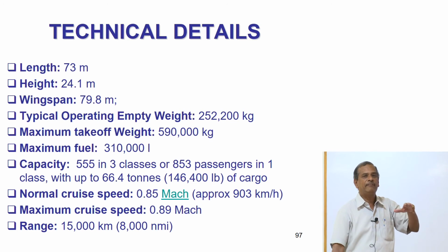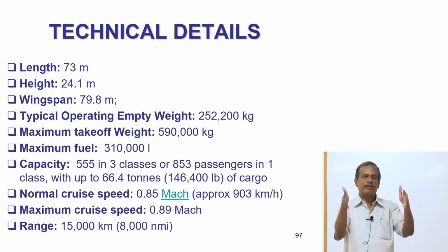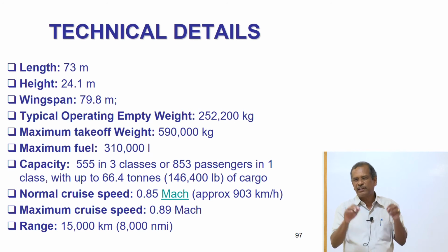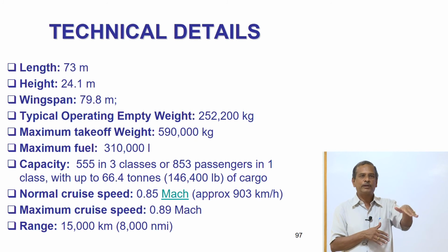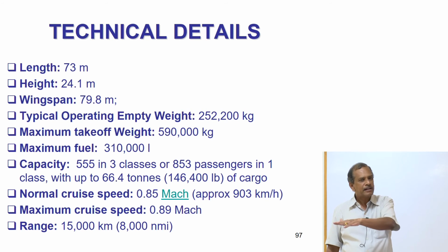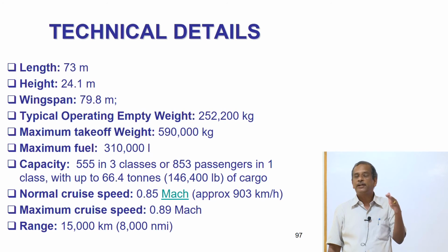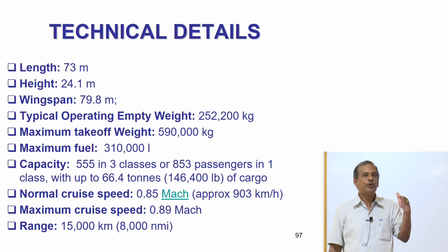Unlike a highway where the traffic wanders, in the case of a runway pavement, they follow a particular path. So, wheel rutting will be along a particular path. The duration of the load application on a runway is only a fraction of a second because the aircraft lands at 200 to 250 kilometers per hour speed. But it reduces speed when it goes to exit taxiways and crawls at a low speed in a taxiway. So, the deterioration in a taxiway will be more than the deterioration in a runway. So, how do I design a sustainable taxiway? What material, what type of pavement, what combination of different layers is again a challenge.